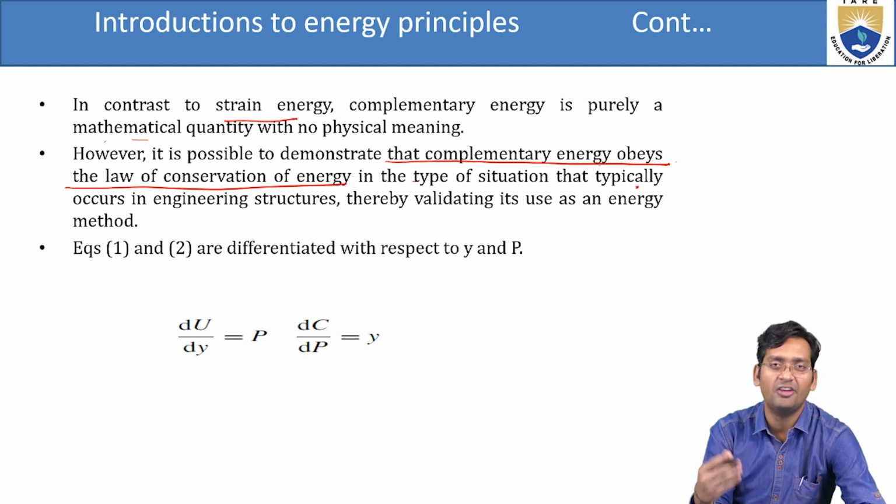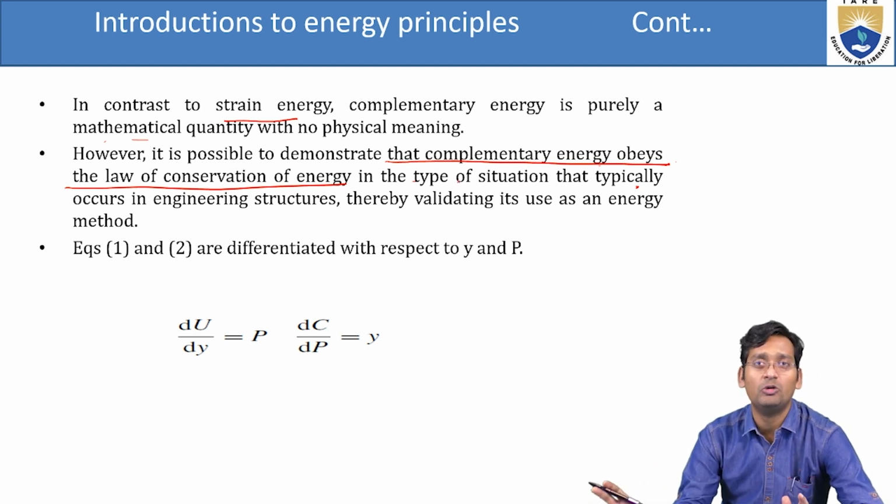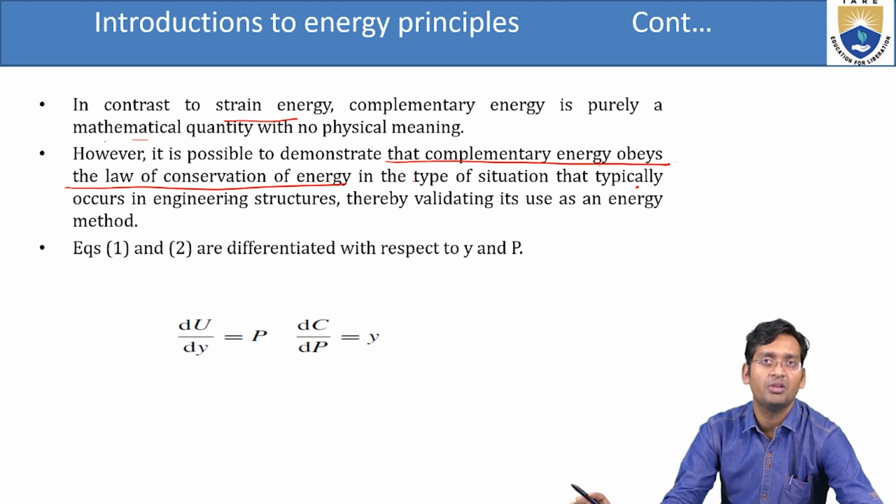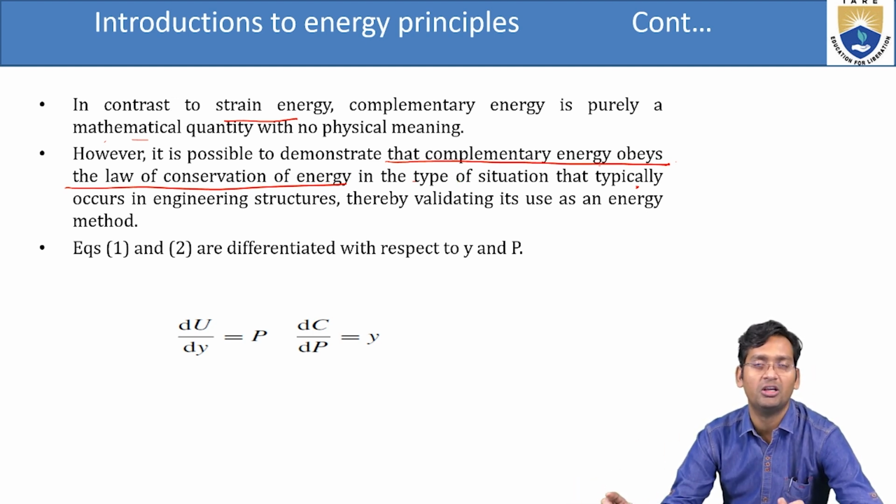That's why in a structure the work done is stored as energy. That follows the conservation of energy, and that helps us to use the complementary energy method. If it's not obeying the law of conservation of energy, then we cannot get the exact solution.